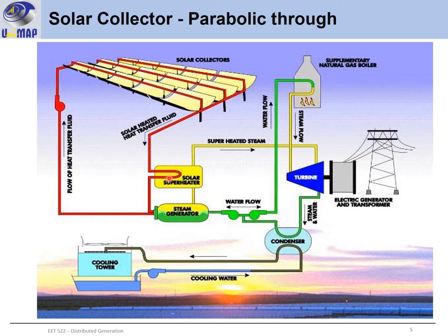If it doesn't receive enough superheated steam at this point, there is a backup supplementary natural gas boiler. The same cool water here will be passed through the boiler, and the boiler will heat up the water and turn it into heated steam and pass it to the turbine. So this is just a supplementary. If the heated fluid from here is not enough to power the turbine, they will use the natural gas boiler to support the operation of this generator. And then we have the cooling tower that pumps the cooling water here, to ensure that this part of the fluid is cooled down.